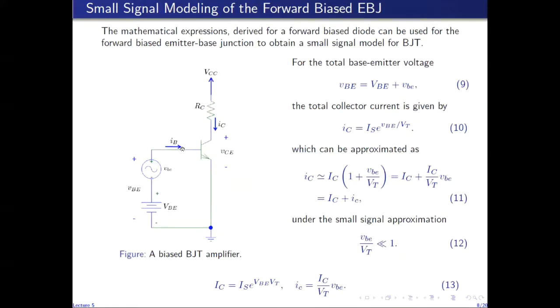So VBE is the voltage of this base terminal with respect to the emitter terminal. When we are looking at the circuit with no DC voltages, so we are only performing the AC analysis of the circuit, between the base and emitter we have this voltage source VBE, which is forcing a current IB into the positive terminal of this port made up of base and emitter terminals.